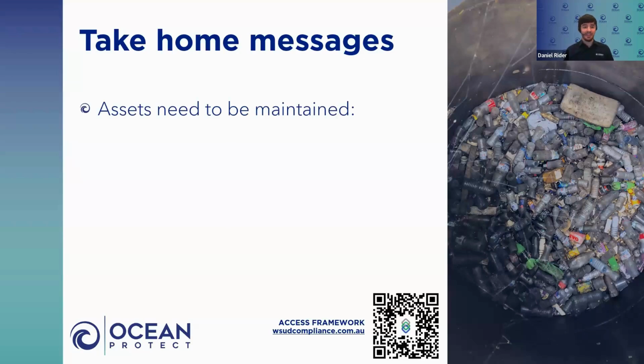Assets need to be maintained. I think that is the main takeaway for everyone from this webinar, is that you need to be maintaining these assets for them to work. Now, for that, you should be looking to get suitably qualified persons to do that maintenance, making sure they have the equipment, making sure they have the experience, making sure they actually can do it. I have seen people previously using garden hoses to try clean out a gross pollutant trap and you'll see a whole range of weird and wacky things happening. So you want to make sure that these people can do the job. Otherwise, it poses a danger to themselves, but also to others on that property.